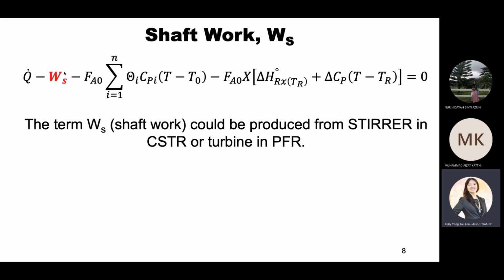Okay? Depends lah, kalau kamu macam soalan test atau soalan exam, kamu kena tengok lah. Kalau soalan stated deem as negligible, then baru kamu letak Ws kosong. Kalau tak, kalau dibagi nilai, kamu kena ganti dengan nilai. Okay, so ingat. Kalau Q, non-adiabatic, kira Q. Adiabatic, tak payah kira Q. Itu beza dia. Ws, kalau diberi nilai, guna. Kalau tak beri nilai, we deem it as negligible.